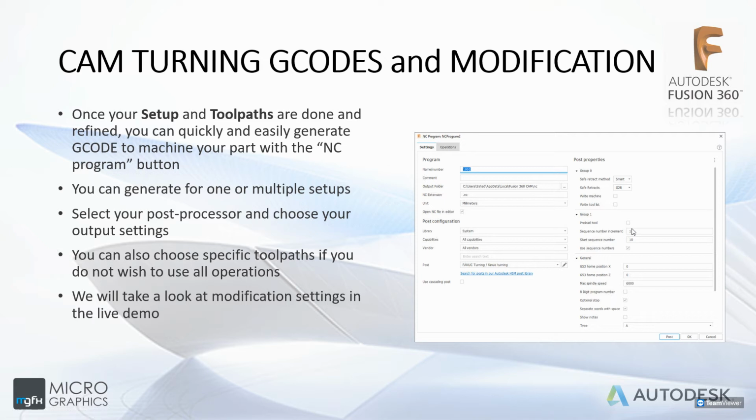Sometimes a simple thing like line numbers can be very problematic. For example, you might have N1 to N500 or N1020, whatever. And some machines are not the newest of machines, and they might have a limit for how long the line of code can be. And a simple thing like the N number in front having more digits than it can handle can really bomb your machine and make it unreadable.